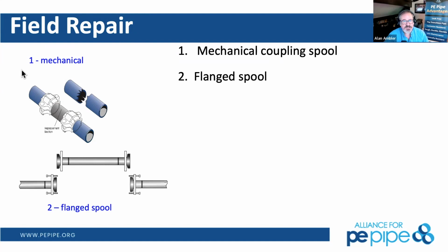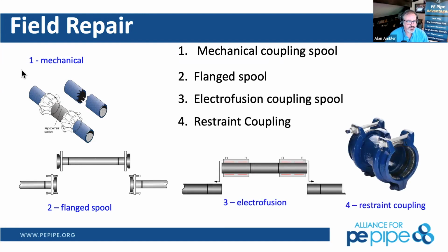So advance all the way to the end of the slide. We'll keep showing you. Mechanical fittings, like everybody that's an operator out there has in your yard already, have been developed to be able to, in the middle of the night, slap right on that potable water main when we've got that leak going. The heavier duty fittings now are considered to be a permanent repair in some instances, depending upon the quality of the fitting.